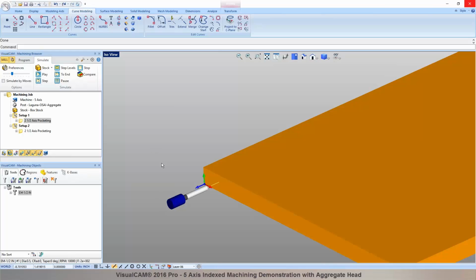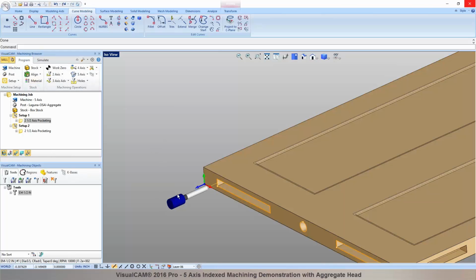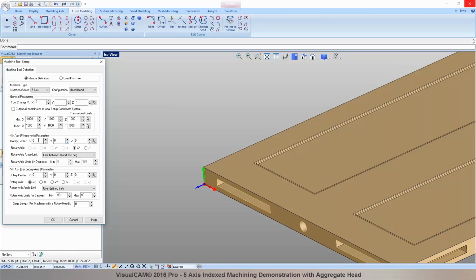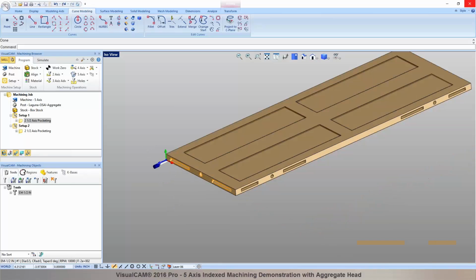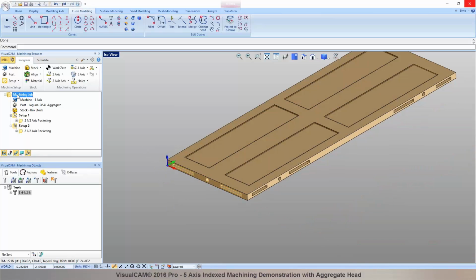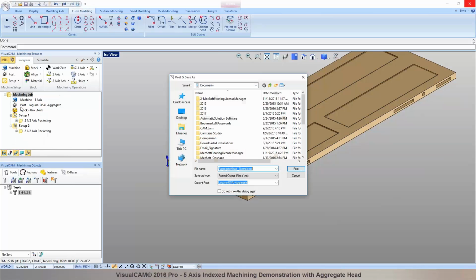And the offset between the spindle, the main spindle axis, you can enter that, the distance between the rotation center offsets right in here. You can say it's offset in the X by a certain distance right there. And that'll get compensated when you post-process it. Now, I'm going to post-process these operations in here, select the machining job, right-click and then select Post All.